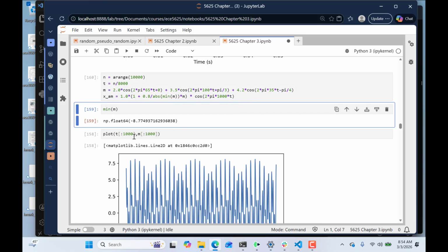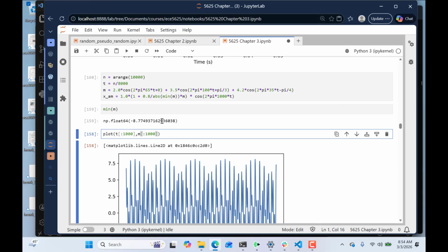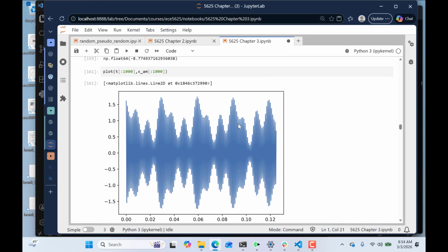So now if I look at my composite over here with the carrier included, which is XAM, I'm now seeing the carrier cycles. I'm seeing the 3 tones of message signal fluctuating around. I'm not at 100%, or am I? Just look at the waveform. Is the envelope closing in the middle?